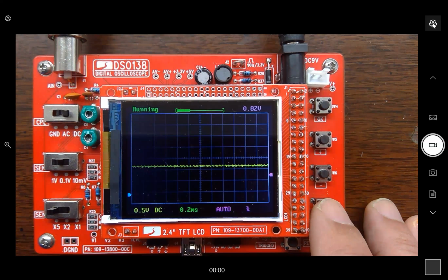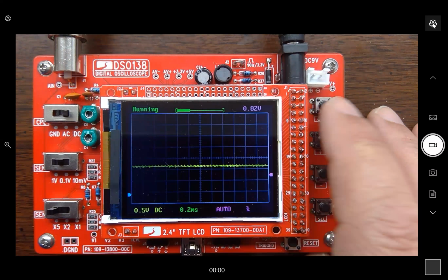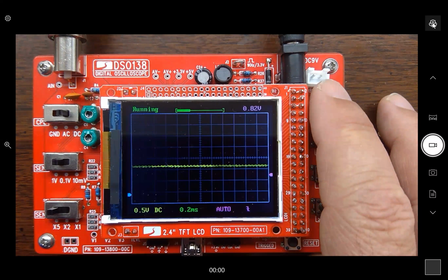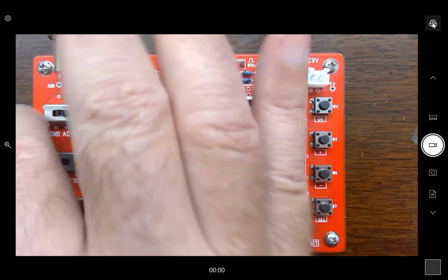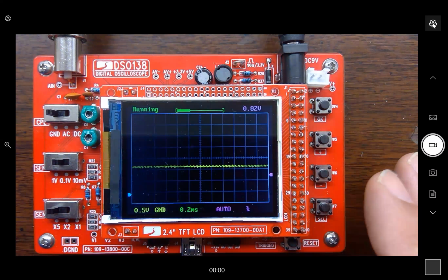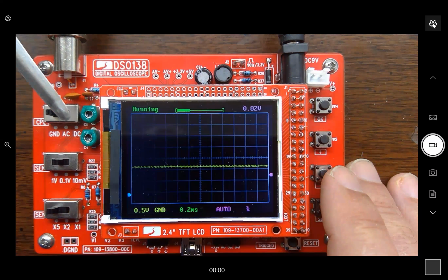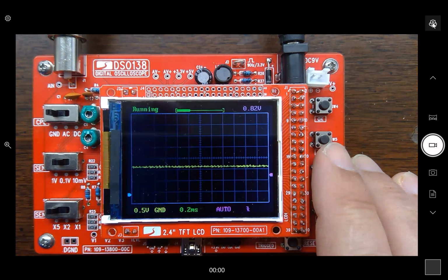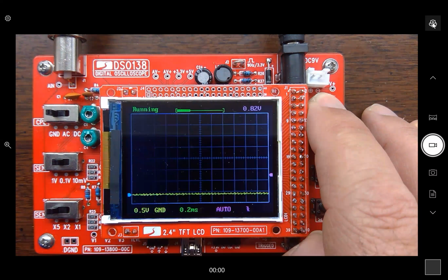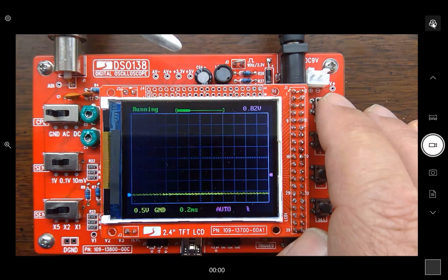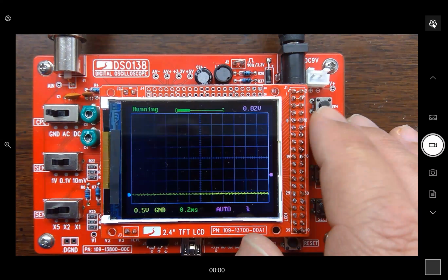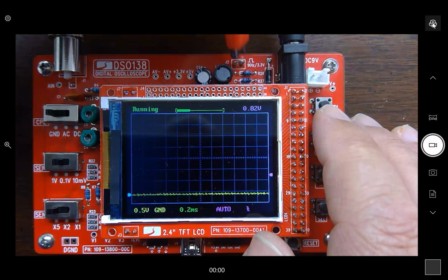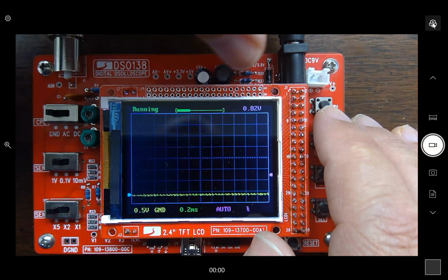And what I'm going to do is press the button over here, and I'll hold it down for a bit. First I need to move this button from DC to ground, and then I just hold this down, and our grounds are now the same. That's what I was trying to achieve. And let's see, we'll reattach this and see if that changed anything.